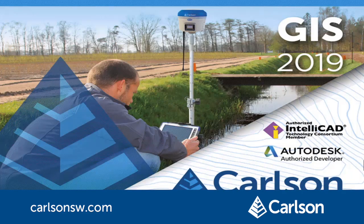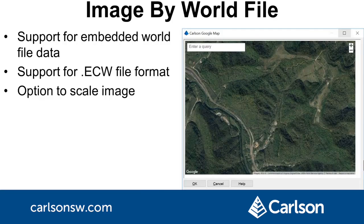Next is Carlson GIS. For drawing georeferenced image files, the program now supports image files with the positions stored inside the image file, instead of as a separate world file. Support for ECW files was added. There's a new option to scale the image in case the image units are different than the drawing units. Also, Google Earth Image has a new option for selecting the image area from a map screen, shown here.